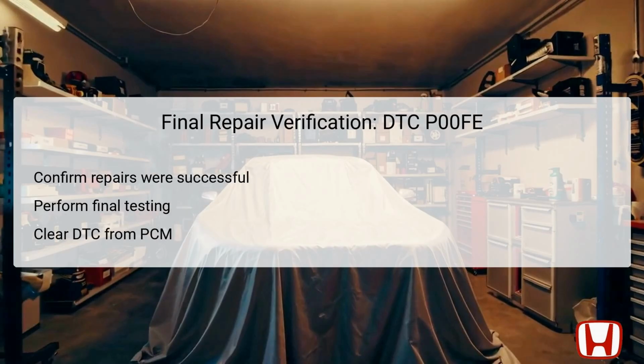Following the troubleshooting and necessary repairs for DTC P00FE, a final verification step is essential to confirm the success of the repairs made. Technicians should run a series of tests to ensure all systems are operating within the specified parameters. This involves verifying that the EVAP system can vent correctly without blockages, and all components are functioning as designed.